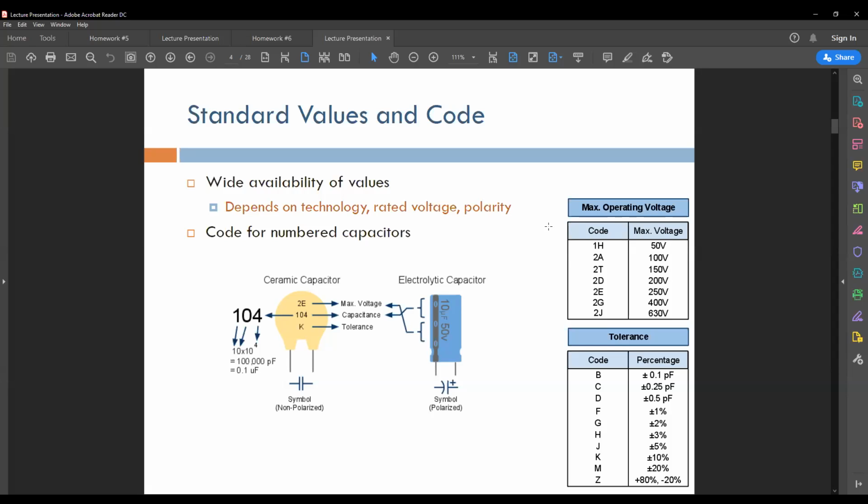If it's a ceramic capacitor, a mica capacitor, a paper capacitor, an electrolytic capacitor, or a tantalum capacitor, each one of these has several values, but they also depend on the company that produces the capacitor. So you'll have a really wide range of values, but there is no real rule to apply like the one that you had for the E12 series or the E48 series that we saw in the resistance.